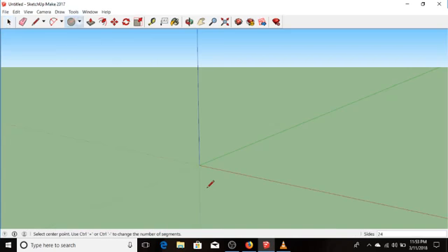C for circle. Right now, see it's set for 24 sides. I want 5 sides. I want a pentagon. I don't want 3 sides, that's a triangle. See it? I don't want 9 sides. I want 5 sides. We'll just snap it to this point here and size it. How big? About 2 meters? 2 and return. 2 meters.